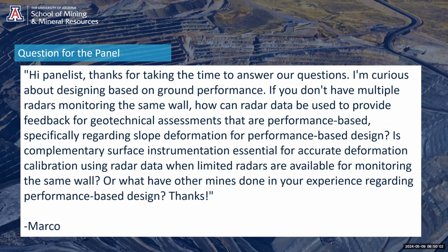Other instrumentation, I believe, is essential. I am completely certain about it. You cannot do all of this just thinking or looking at radar data. InSAR data, prisms, extensometers, inclinometers, piezometers, everything should be taken into account for the analysis of your mine and designs, and how successful they were, and what changes you may need to introduce in order to get your mine back to compliance, to the performance that is expected.